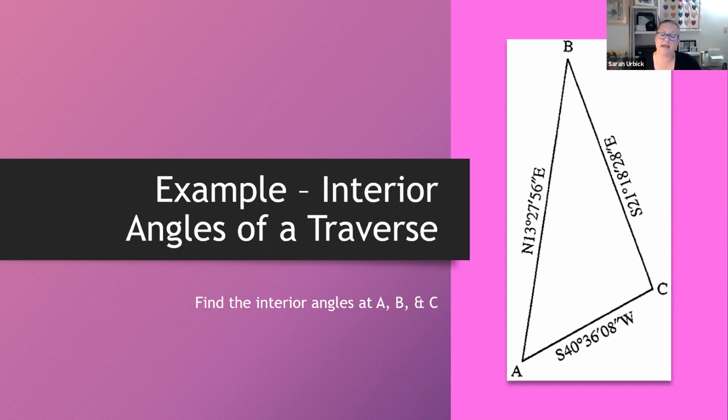One of the ways I can is I can get a reference point. I can find a benchmark. I can say the white mailbox labeled such and such. I can use that as my reference point, something that's not going to move a whole lot. So I don't want to use the cat sitting on the corner. I want to use an actual location. It could be a manhole, even a lid.